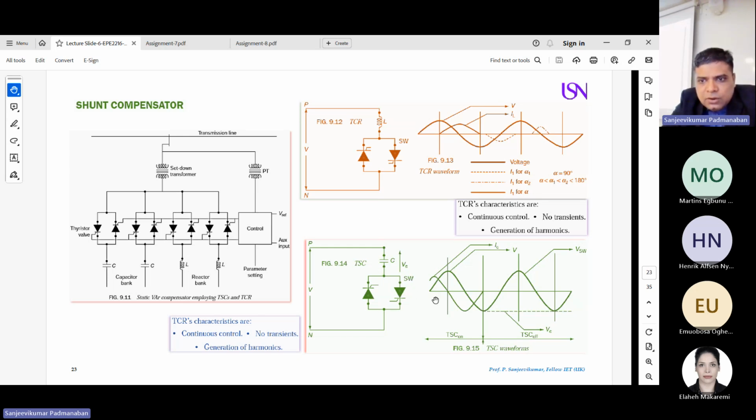In this case, you can have a look. This is your voltage, you are sending in voltage. By controlling these devices, you can see the current is shifted to leading. You can make this current unity, lagging, everything by controlling these two devices. So you have absolute control on your current for unity power factor, lagging power factor, and leading power factor by using thyristor controlled capacitors, where you connect the capacitors in series with anti-parallel connected thyristors.